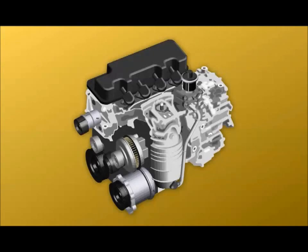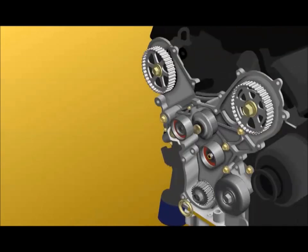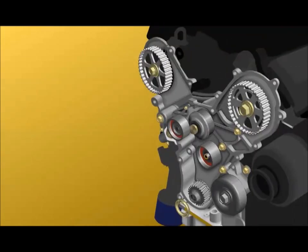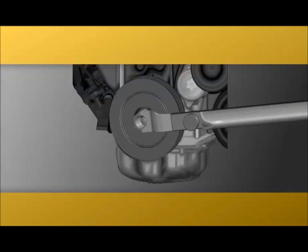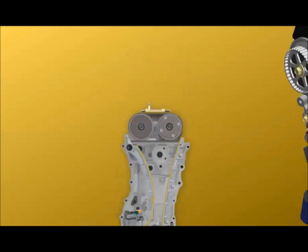If this eliminates the binding, check all accessories for binding. If the binding remains with the accessories disconnected, remove the timing belt or timing chain and check for binding again. If the binding goes away with the camshafts disengaged, check for binding in the camshafts and cam drive system.